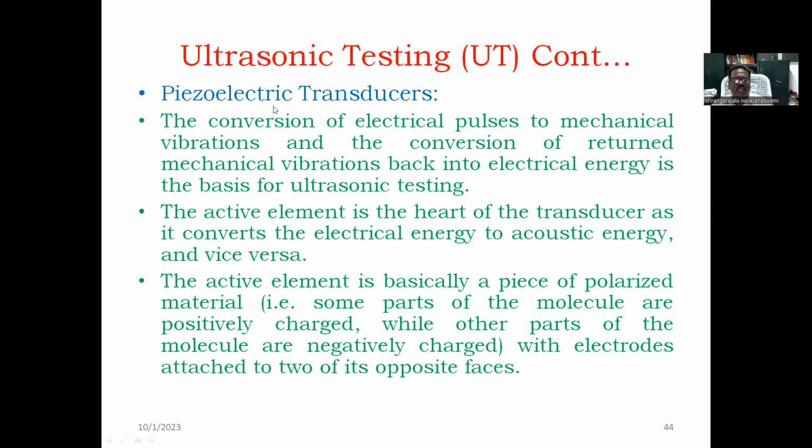Piezoelectric transducers: the conversion of electrical pulses to mechanical vibration and the conversion of returned mechanical vibration back into electrical energy is the basis for ultrasonic testing. The active element is the heart of the transducer as it converts the electrical energy to acoustic energy and vice versa.